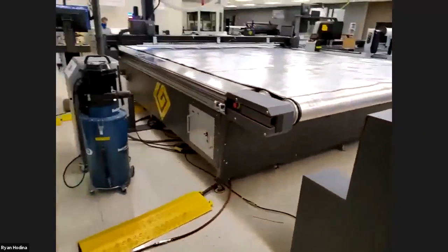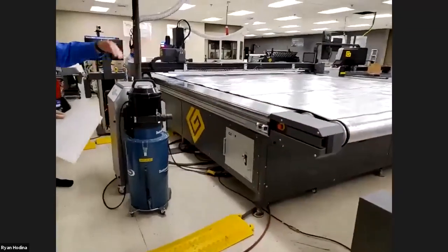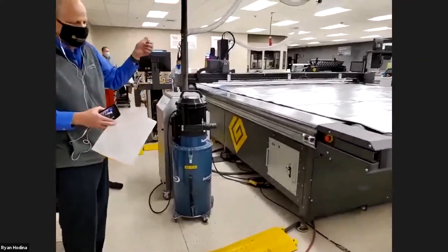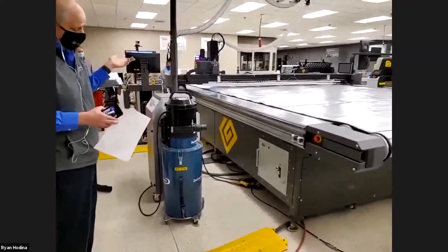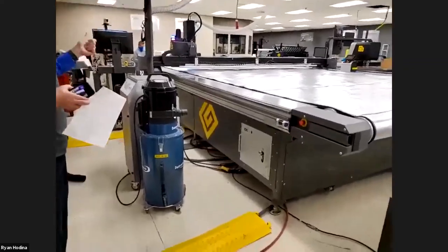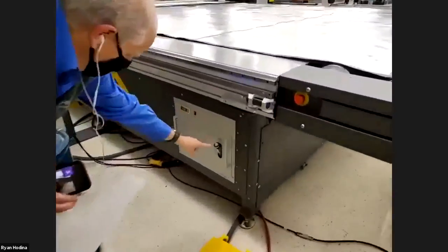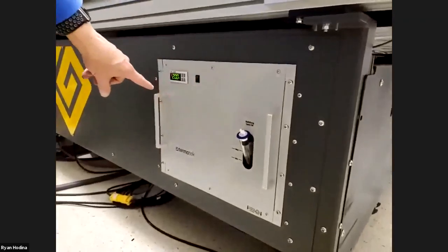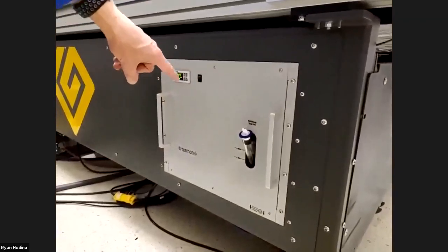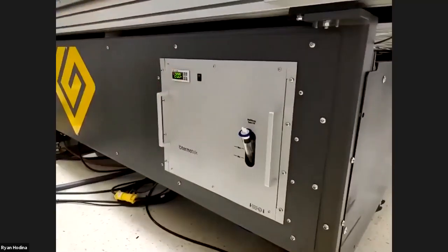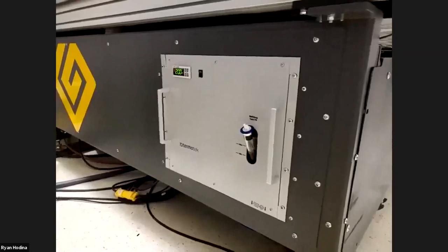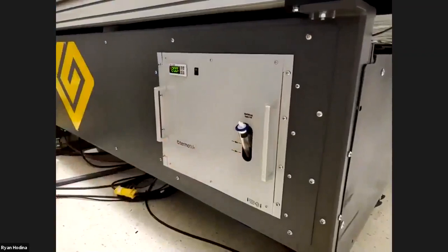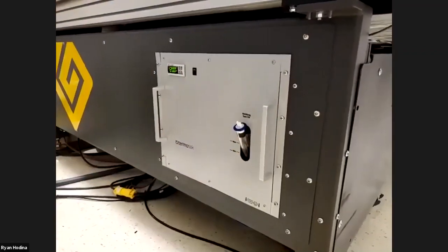So now we're at actually, this is the feed side of the table, and this is termed the datum side or the reference side. And what you're looking at is a couple of items that are related to whether or not you have a laser or a router, or both. So if a customer orders a laser or router, we use a liquid cooling system. So this is a chiller. This is built right into the panel for the system, and we're providing cooling liquid from here to the laser head or to the router. So it's a closed loop system. It has a sight gauge on it, makes it real simple for our customers to keep the high powered laser or the router cool while it's running.